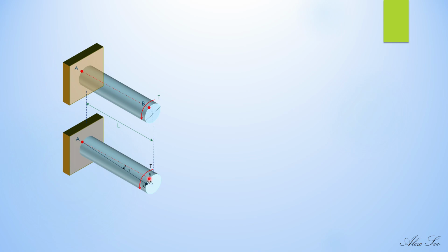What is this angular displacement here? This angular displacement can be determined by taking the radius multiplied by this theta, r theta. Arc length is equal to the product of r, the radius, and the angle theta. Or the arc length of B to B prime can also equal the length L times the angle gamma.